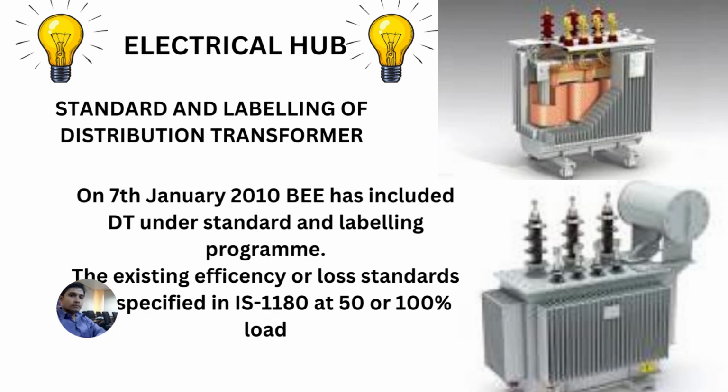It is important to note that before 2010, there was no standardization and labeling of distribution transformers. But from 7th January 2010 onwards, BEE, Bureau of Energy Efficiency, has included distribution transformers under the standard and labeling program. Now, the existing efficiency or loss standards are specified in IS 1180 at 50% or 100% load.